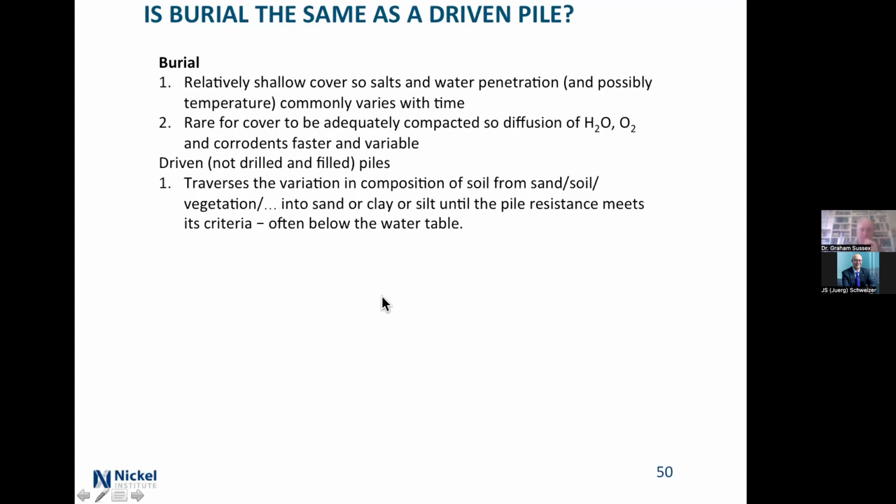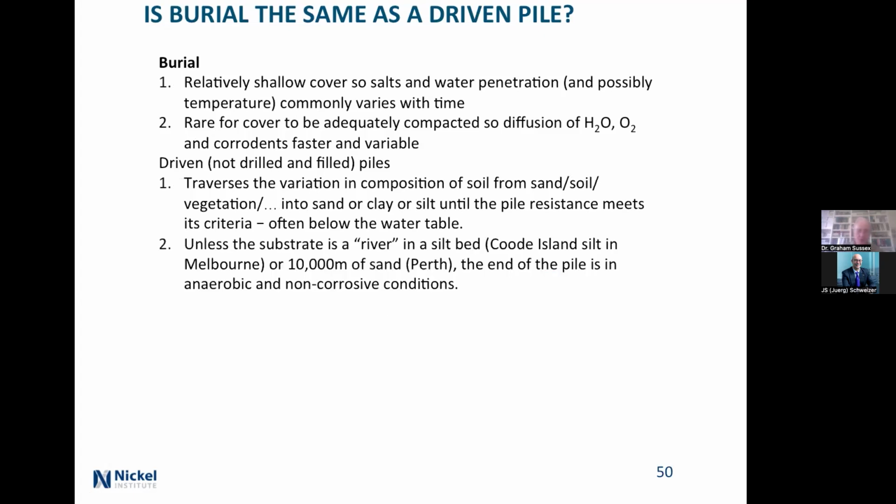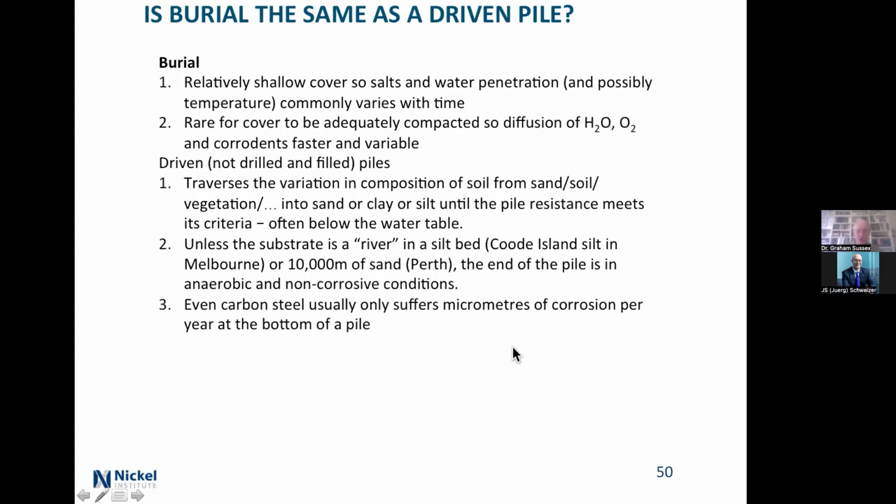So let's drive in the pile. It's going in through the composition of the soil from the top down through the sand into whatever's there until the pile resistance basically says that's it. That's often going to be below the water table, but even if it isn't, what's going to happen? Unless the substrate's a river, a silt bed like the Coode Island Silt in Melbourne, or the 10,000 metres of sand you've got in Perth, then the end of the pile is in an anaerobic and reasonably non-corrosive condition. Even carbon steel usually only gets micrometers of corrosion. So burial and driven piles are definitely not the same, and driven piles basically survive a lot better.